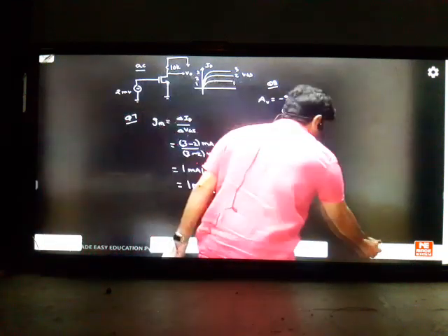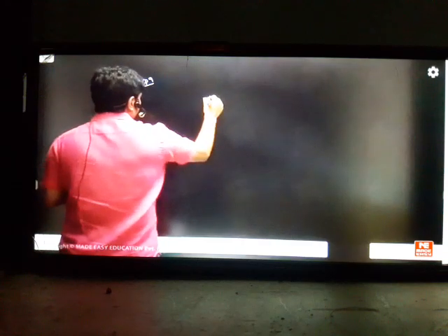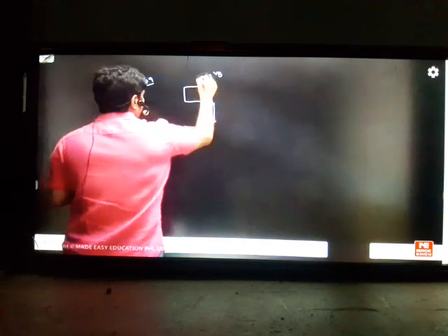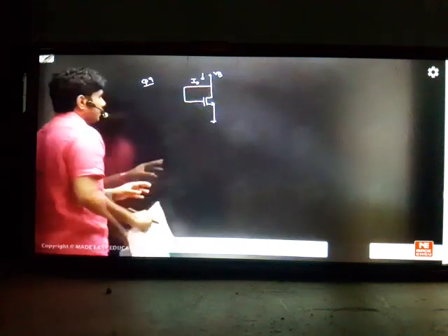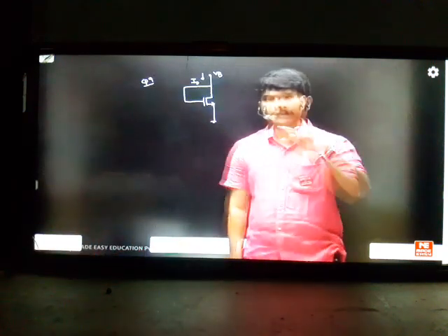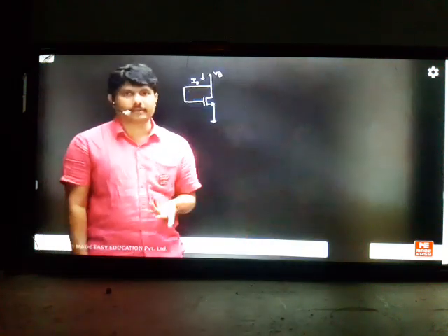So let us understand the question. He has got a MOSFET like this, connected to VB, and he made a short like this, saying that this current is your ID. Whenever you see it like this, every student knows that in our class it's current saturation. It's not required to repeat this story many times. Whenever there is a short like that, the circuit works under the biasing of current saturation, because in current mirrors and inverters we have seen this, and we are developing this concept.